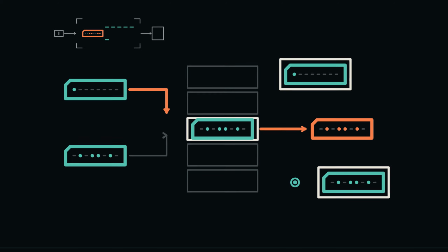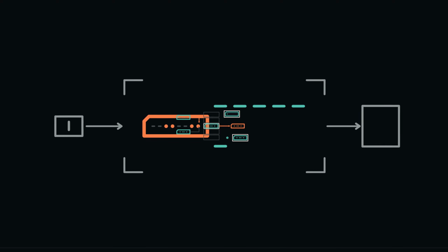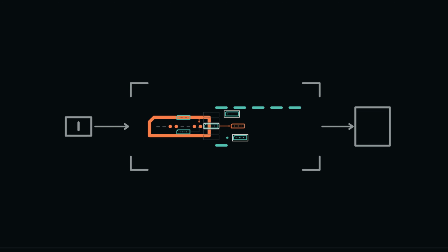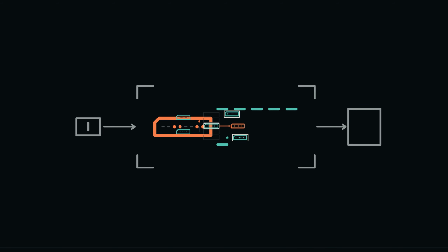A write is a controlled state mutation. Establish the address, stage the data, then commit exactly one selected byte. A read is an observation followed by transport. Establish the address, capture the selected byte in MDR, then deliver it to a destination. The ledger preserves what existed before and after every edge, so no animated handoff needs faith. We can now store values and recover them.